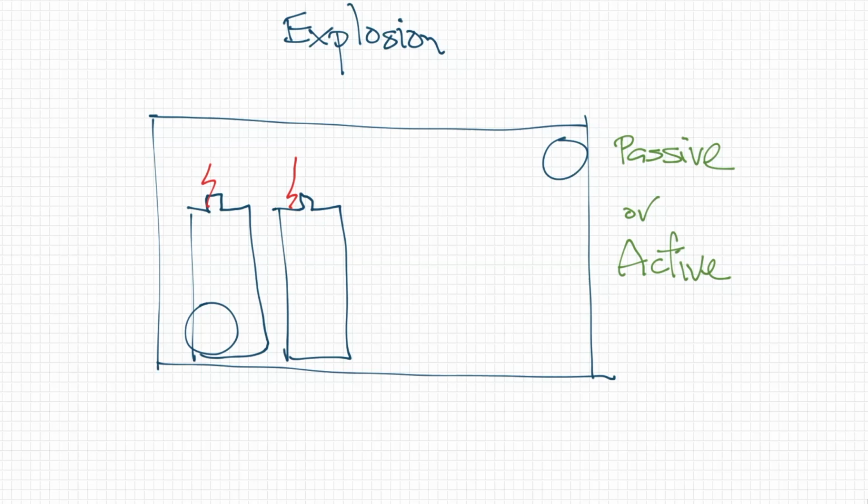That means you've got moving parts, noise. You also need to consider that it is an arc source if it fails. So if you had active ventilation, you'd want it to be down here somewhere, below where it could be a source of ignition, not at the exit point. It is possible to do active ventilation as long as you have an alarm in case of failure.